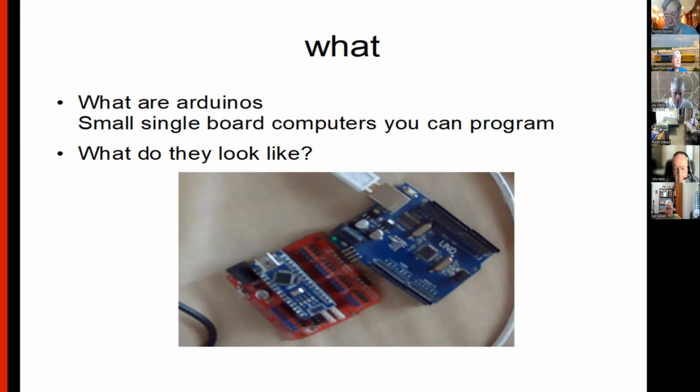On the Uno, you've got plenty of pins, but for each signal you need a ground, and there's only 2 or 3 grounds on there. So you've got this one ground coming out to a ball of solder with 14 wires coming out. And I don't like that. On the breakout board, the blues are the ones with the signal, the red is the power, and the black is the ground. So every signal that you're dealing with, you've got the signal, the power, and the ground. Both of these use 5 volts. I'm told that the new ones coming out are using 3.3, which will change a bunch of the stuff I use, but this is just the overview of what it looks like.